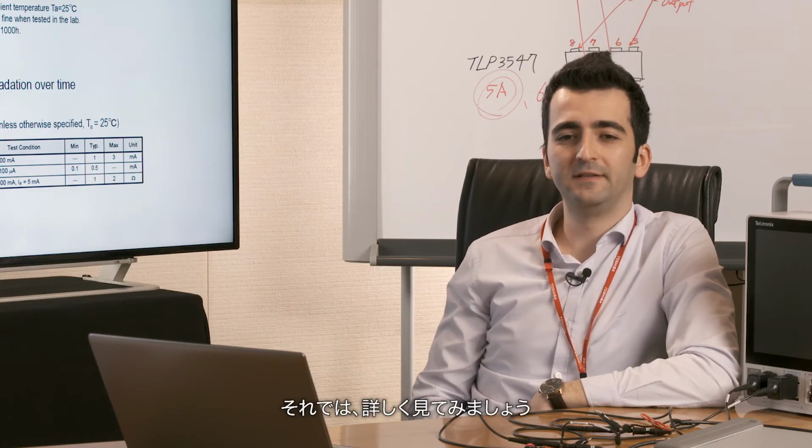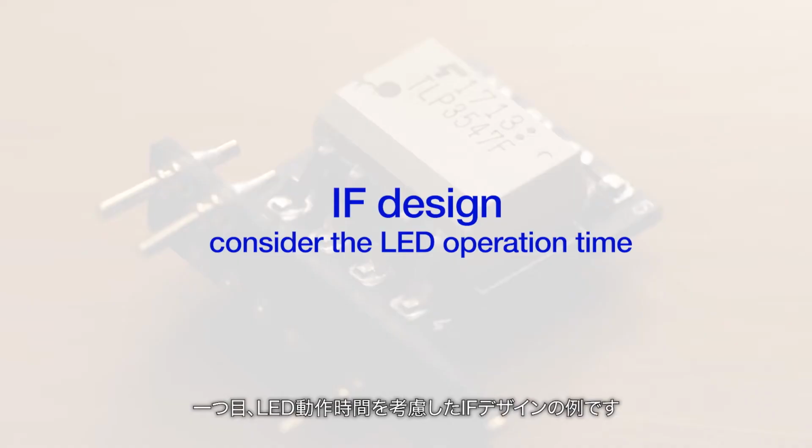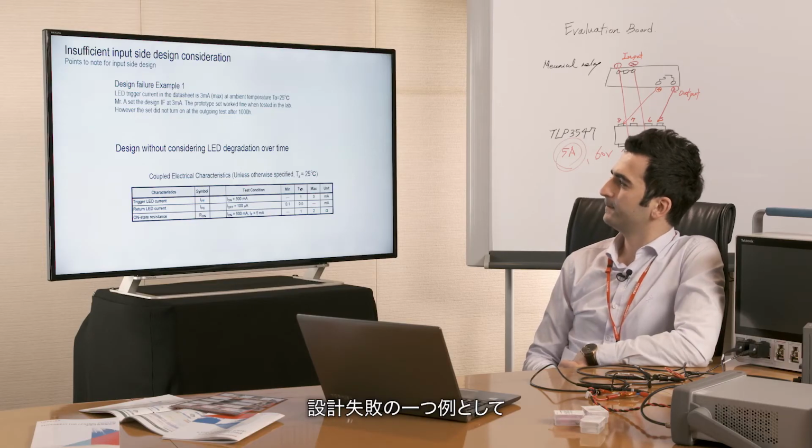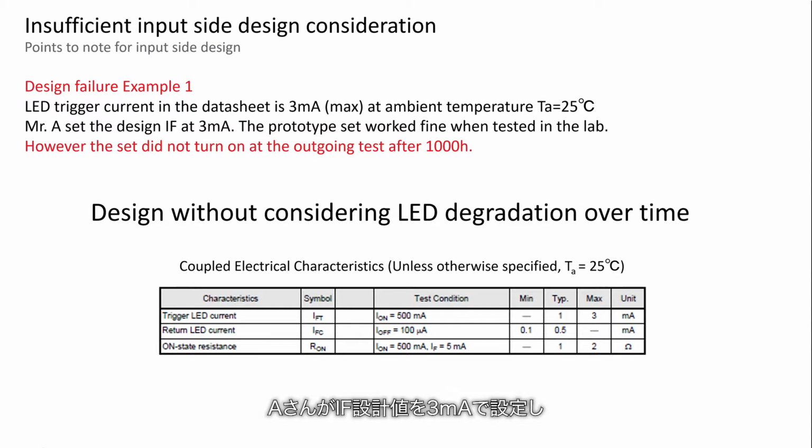Let's look in more detail at design considerations. Considering LED operation time in IF design. In design failure example 1, the LED trigger current in the datasheet is specified as 3 mA max at an ambient temperature of 25 degrees. So Mr. A set the design IF at 3 mA and the prototype set worked fine in the lab.